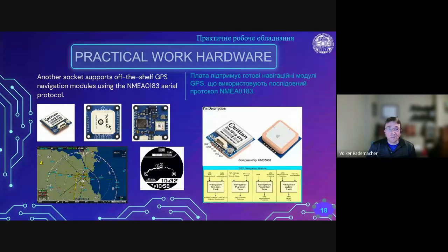The accuracy depends on the satellite strength and the number of satellites that it sees. Even if it has a lock, it might wander around by 2, 3, 5 meters. So every instantaneous position that you're getting is accurate only to this amount.